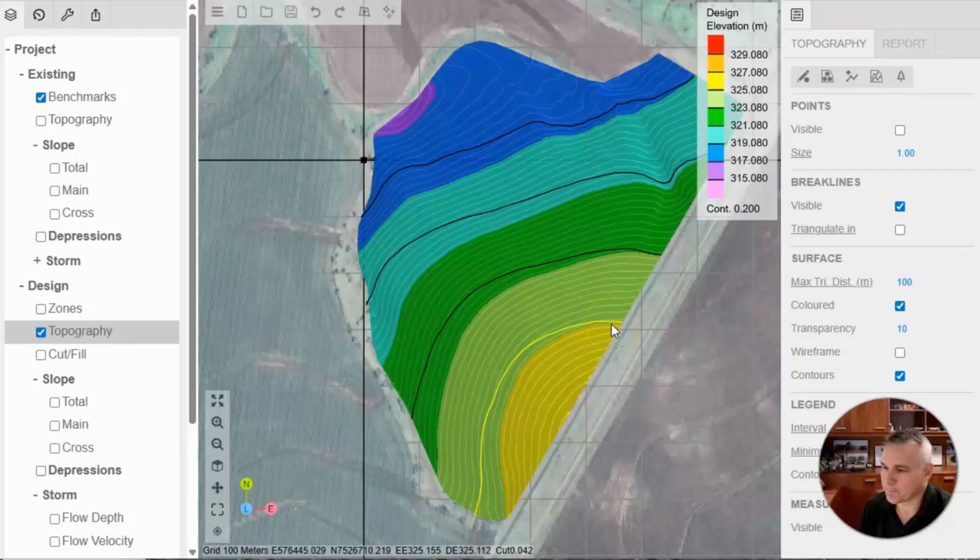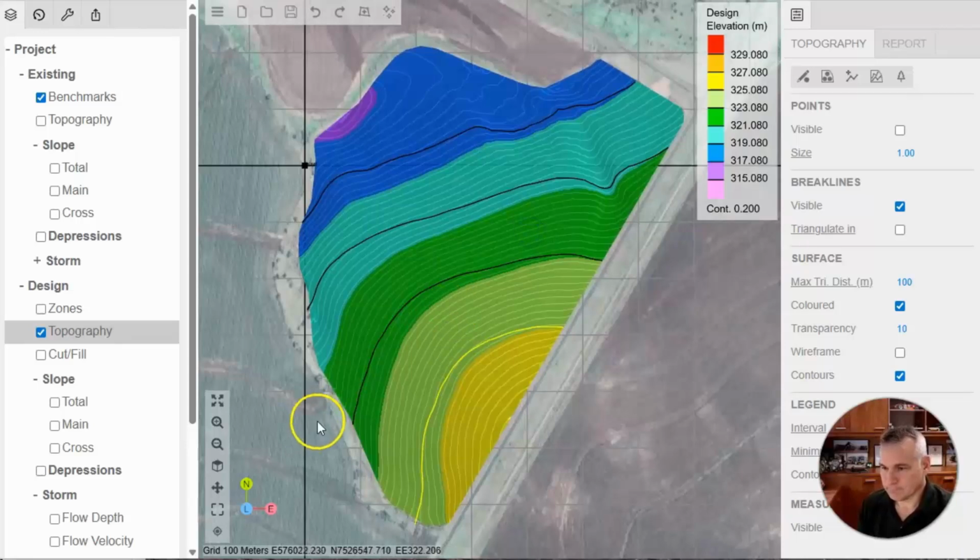The next iteration on that is putting vertical control on these. Instead of just providing horizontal guidance lines, we can provide 3D control files that go into the earth moving machines to control the blade height as they're building this. In this case, the client just wanted guidance lines.